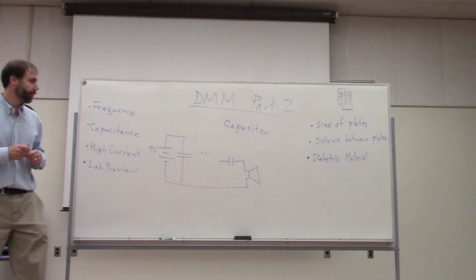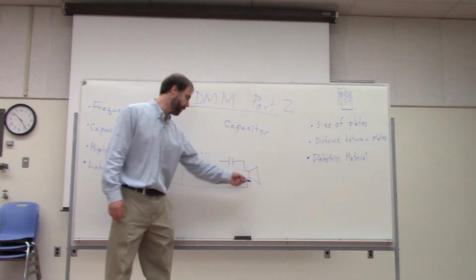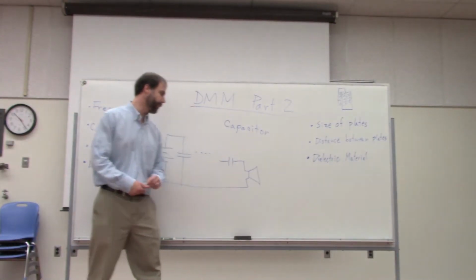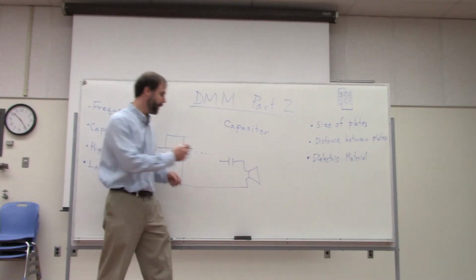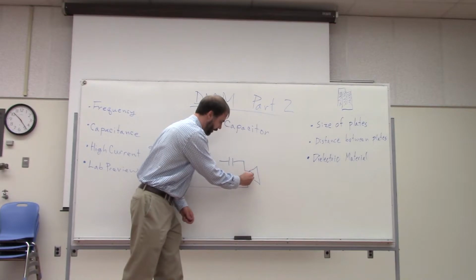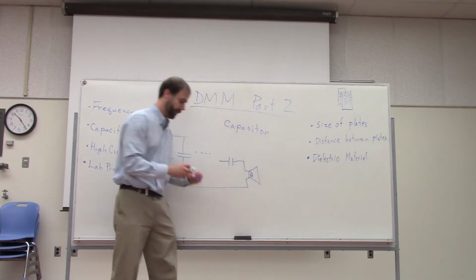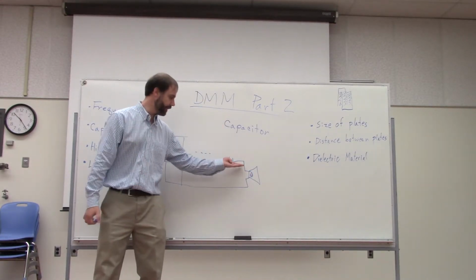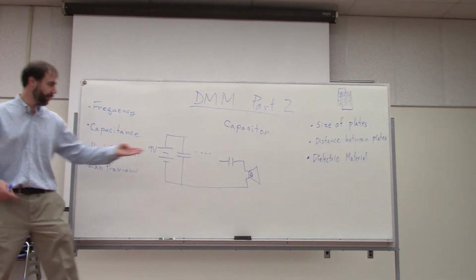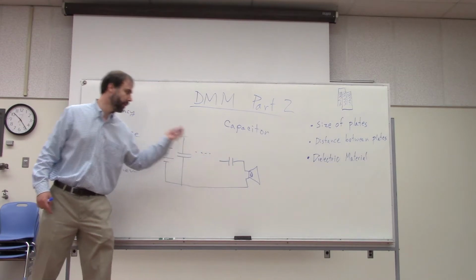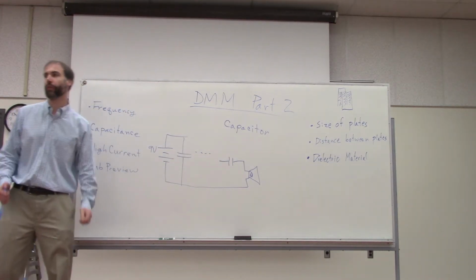And if we had a constant voltage going to our speaker, that would be bad for a couple of reasons. First of all, remember, the speaker is just essentially a coil of wire, okay? So if we had a DC signal on a coil of wire, there would be very little resistance, and that signal would be pushing a lot of current through that wire.